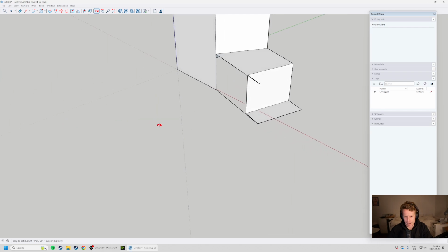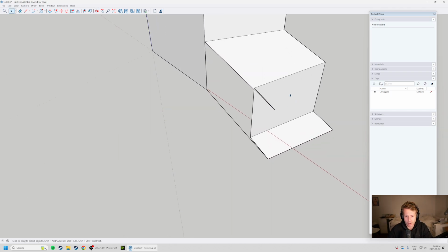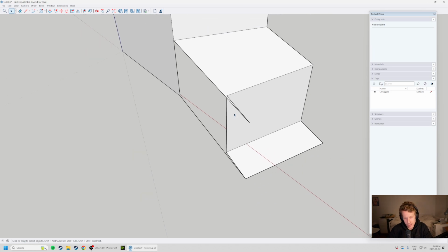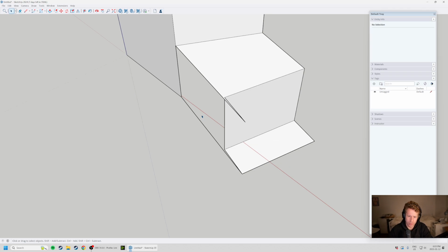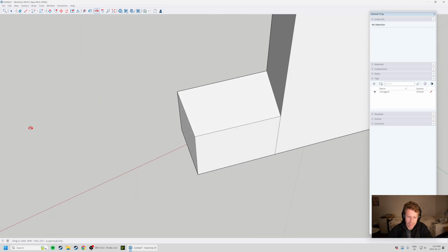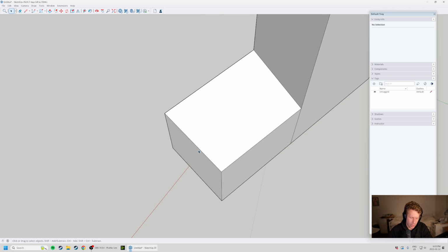So I want us not to get frustrated, but there are definitely some challenges in SketchUp. So when we are modeling, we want to model things in a certain way. A different way to do this, let's say we wanted to cut 5 meters off of our building. I'm going to undo those. So I'm going to tap undo twice. Let's say we wanted to do this a slightly different way. You can't really push-pull that edge. It doesn't really work how we want it to. So I'm going to suggest that we actually cut the piece off.